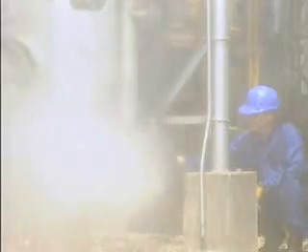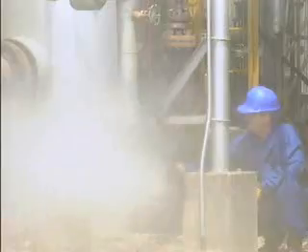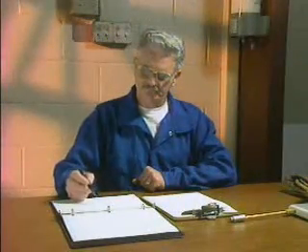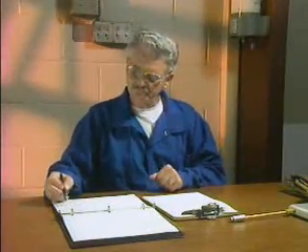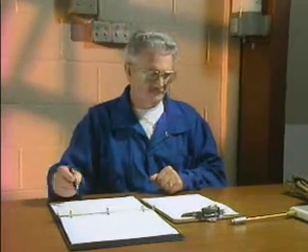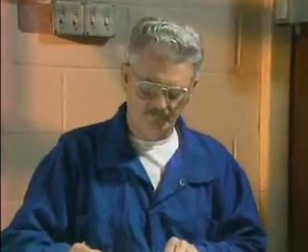Another task that's usually part of a trap station survey is making sure that the trap strainer has been blown down. If this hasn't been done, opening the strainer blowdown valve one full turn and then closing it will usually provide enough flow to clean out the strainer. Finally, you should keep a record of the trap station's performance or operating history. Reviewing the operating history may reveal specific problems that should be checked during a survey of an individual trap, or it may clear up questions about how the trap station has performed under certain operating conditions.